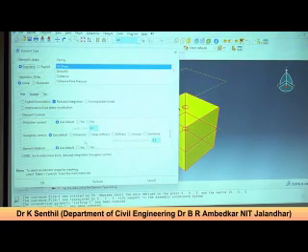So mostly what we do in simulation is reduced integration. Reduced integration is computationally cheaper and better, but it creates hourglass problems, excessive distortions. To eliminate this you can use full integration. But when you use full integration, there is a high chance of shear locking, because the shear stress and strain are predominant. So there it's shear locking, and here it is hourglass.